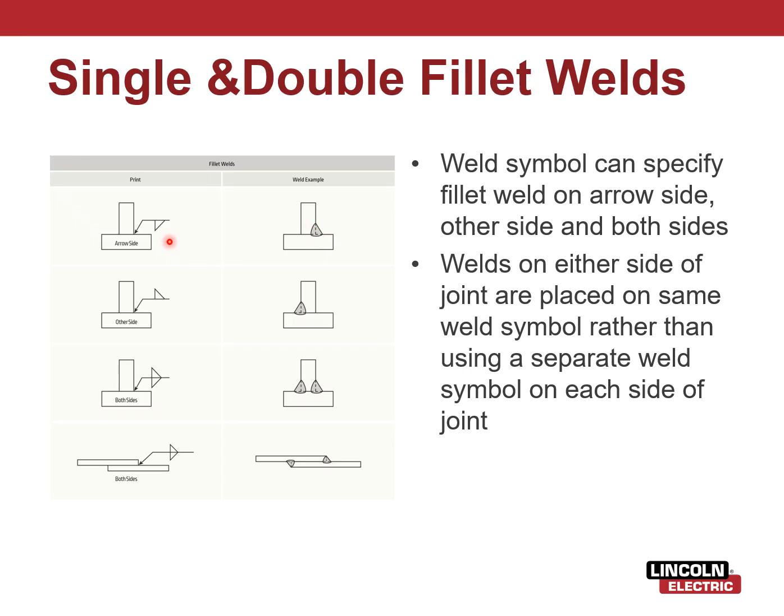Okay, so your assignment this week is going to be looking at symbols like this and or images like this, and then putting the weld symbol on the correct side of the reference line. So pay attention. Arrow side is going to be on the bottom, so it's going right where the arrow is. Other side, it's going to the opposite, both sides. Again, the vertical line is centered, the slanted line is to the right, and that's going to be a weld on both sides. And here's that same example just on a lap joint. Most joints have two sides to them, so that's why we always have that opposite.